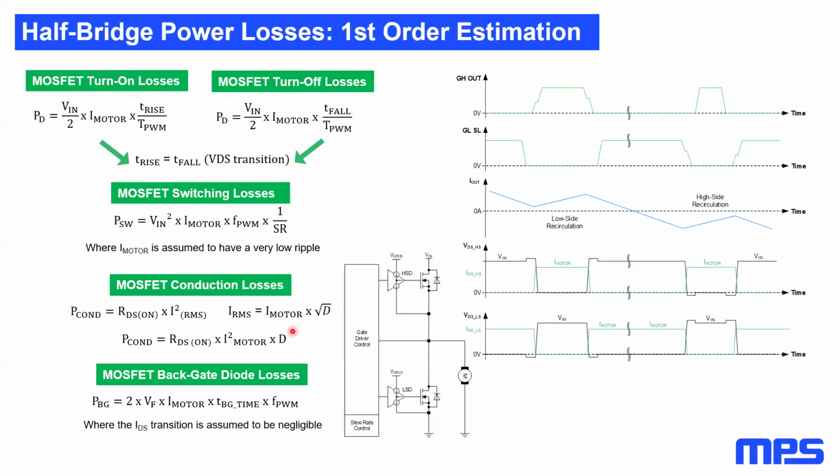Again, you can find a lot of formulas if you don't want to do the exercise. I suggest the exercise. I'm a fan of that. Or you can measure it, if you have access with a current probe to the DC link cap, if it's big enough. But the question is very relevant, because the RMS losses, especially in an aluminum capacitor, should not be underestimated.